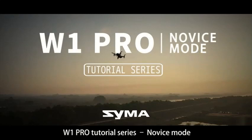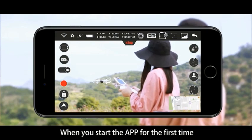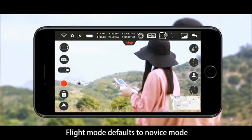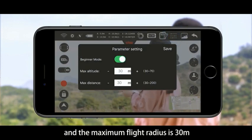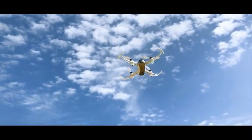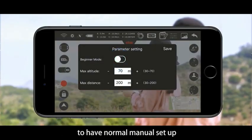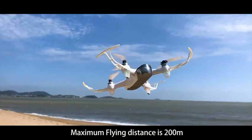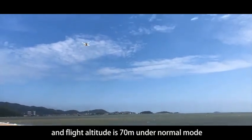Tutorial series: Novice Mode. When you start the app for the first time, flight mode defaults to novice mode. The maximum flight altitude is 30 meters and the maximum flight radius is 30 meters. You may switch off the novice mode after you have normal manual setup. Maximum flying distance is 200 meters and the flight altitude is 70 meters under normal mode.